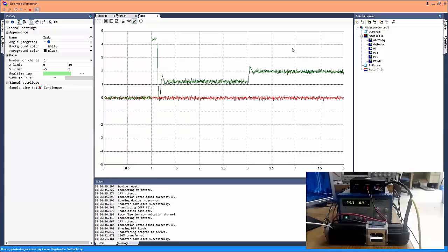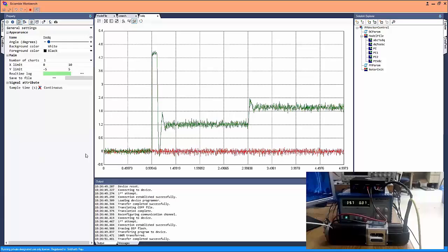And if you look at the ISD and ISQ currents, in the case of the induction motor vector control, we had an ISD current component which was non-zero because the stator currents established the rotor currents, which in turn established the rotor flux linkage. But in the case of the permanent magnet synchronous motor, we have a permanent magnet on the rotor, and hence the stator does not need to establish any flux in the air gap. Thus the ISD current is going to be zero.